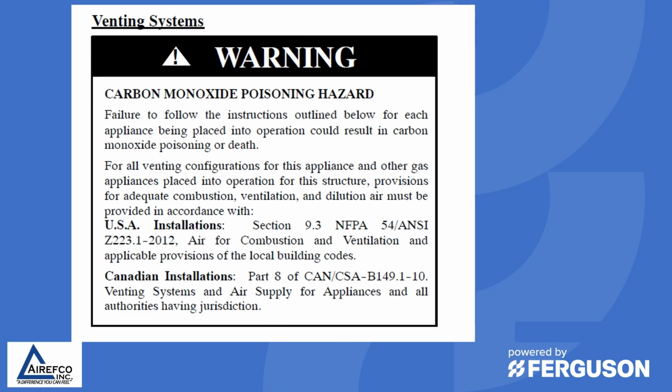So we can't stress enough the warnings that you find in the installation guides for carbon monoxide poisoning. Anytime that you put a gas appliance in an occupied structure, you run the risk of having carbon monoxide poisoning. And it is a hazard that you as a technician and installing contractor need to take seriously so that we don't have any issues with the installation.